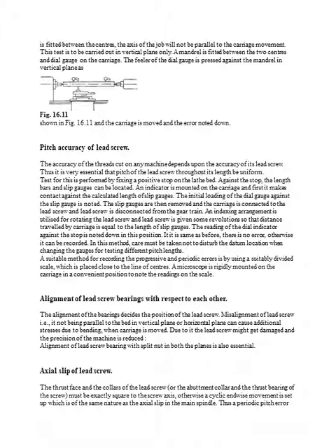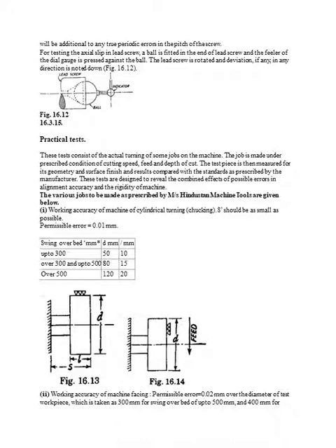Because it is connected to the main spindle, when the main spindle is rotated, the lead screw is also rotated when it is connected with the half nut arrangement. So it should be checked periodically.